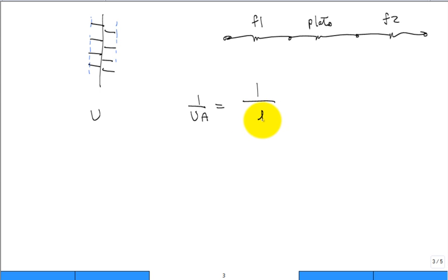What you have is the convection coefficient on that one side, then the area for heat transfer on the one side, and then because it's a thin surface, you have the efficiency overall for the one side. And we calculated that overall efficiency.